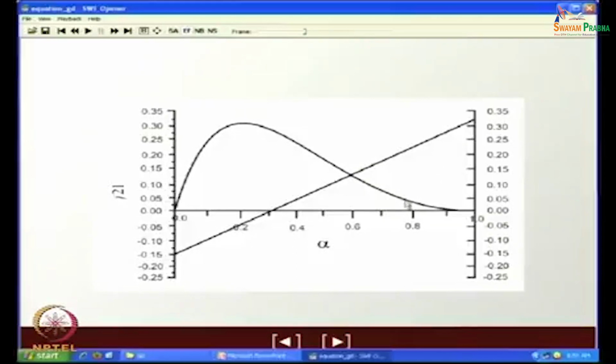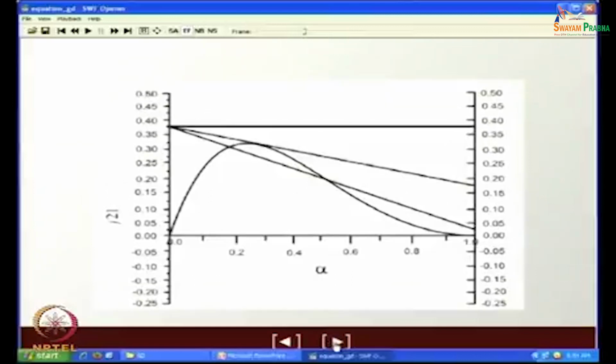as expected. Here we find that alpha occurs at a higher gas velocity, because for co-current downflow, if gas velocity is not quite high, we cannot obtain a stable flow pattern. Okay. So, this was the point of intersection for co-current downflow. Now, let us take up counter current flow. Counter current flow with gas up, liquid down.